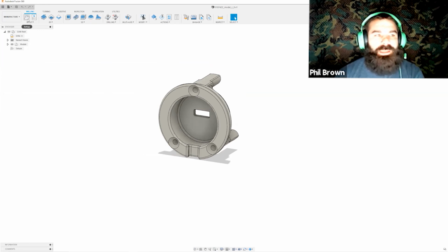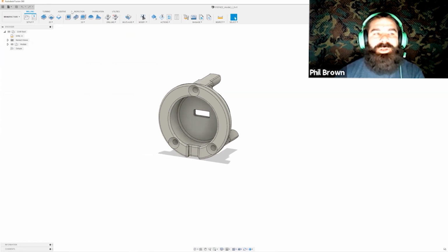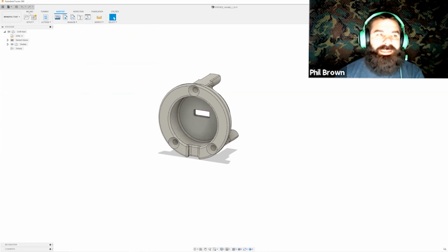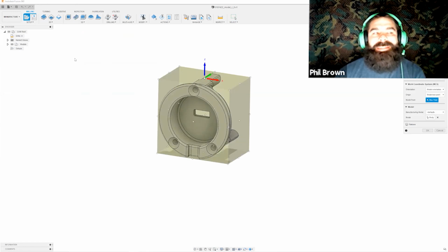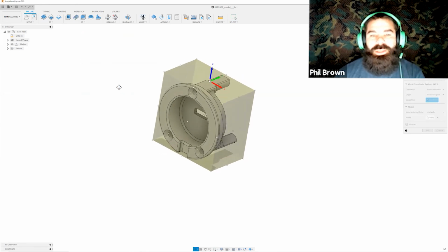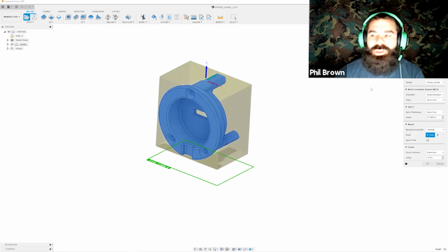Right out of the gate in Fusion 360, you're going to see a couple of different things here. One, I always have to have a setup, and two, I have tabs across the top of my screen for different manufacturing styles. I know we did get an FDM question earlier. We do have the ability to do additive slicing inside of Fusion 360, depending on your machine. But to start with, I'm going to sit in milling. Even though we're going to do this as a turning operation, it's not going to make a difference out of the gate. So right from this beginning point, I'm going to switch from milling to turn mill.